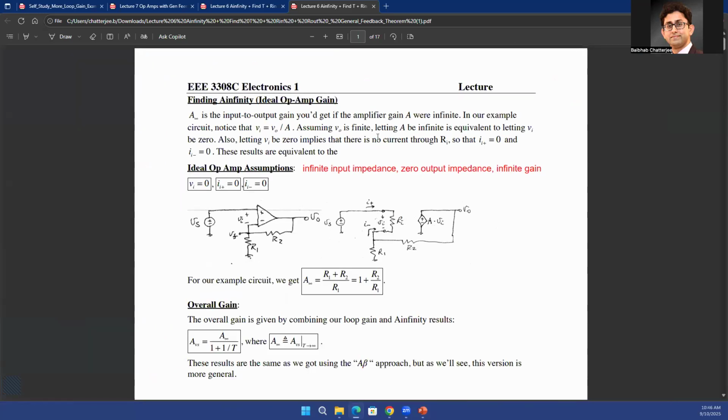All right, and we're going to create a simplified method using which you can solve any problem related to real op-amps. For example, depending on the circuit that you have, you can always figure out how much current actually goes through that R2 resistor, and how much current actually goes inside the op-amp if an input impedance is given. Just consider it as a very complex nodal analysis problem instead of a simple nodal analysis problem. So you can always do that.